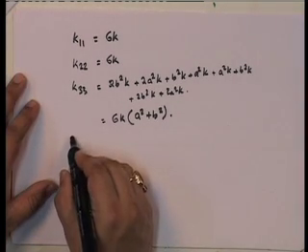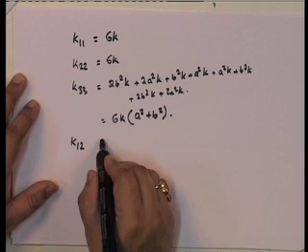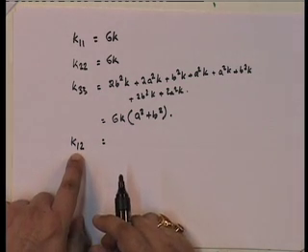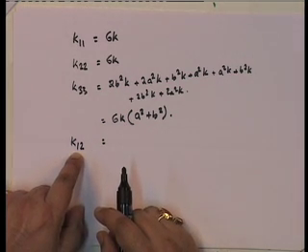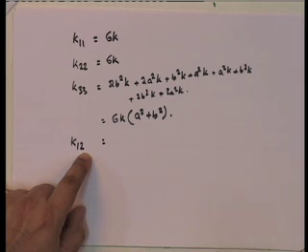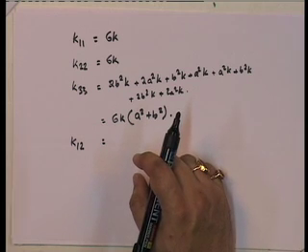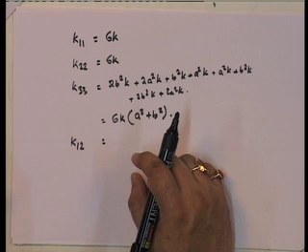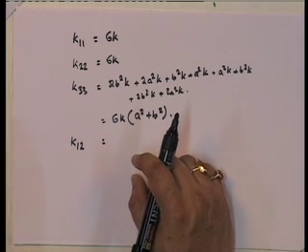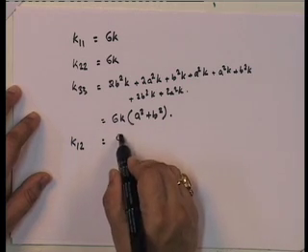Let us now find out K12. K12 is what? The force at 1 due to displacement at 2. So, for K12 the displacement is at 2. So, this is the real one, and this undergoes this displacement. So, let us find out what is the work done. All the forces are in this direction, displacement is in this direction, work done is 0.